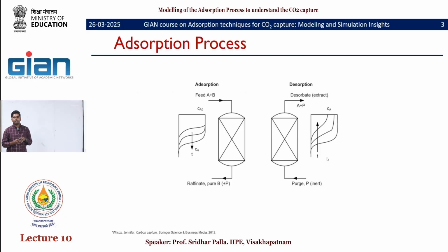Due to the reduction in the interaction, the gas molecules that are adsorbed in the bed will come out. That is the physics behind purging. We can also reduce the pressure in the bed. That is how pressure swing adsorption works. If the gas is stored at high pressure, for example 10 bar, and we release the pressure valve at the exit to atmospheric pressure of 1 bar, whatever gas is stored will come out. That is a pressure swing.